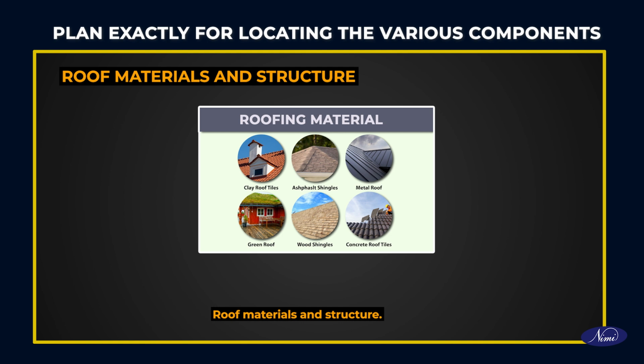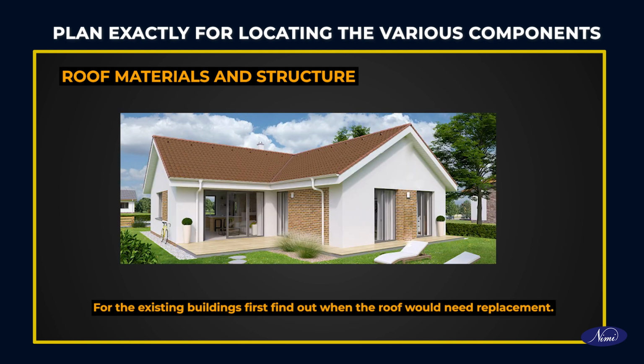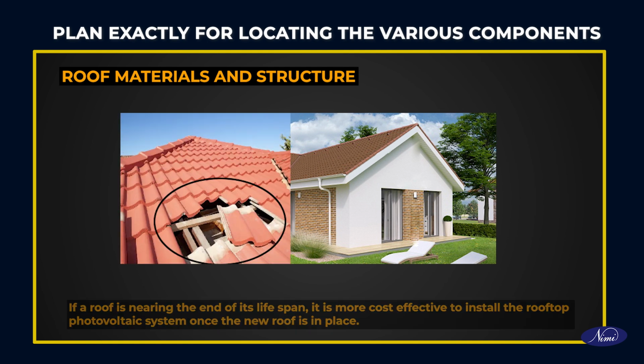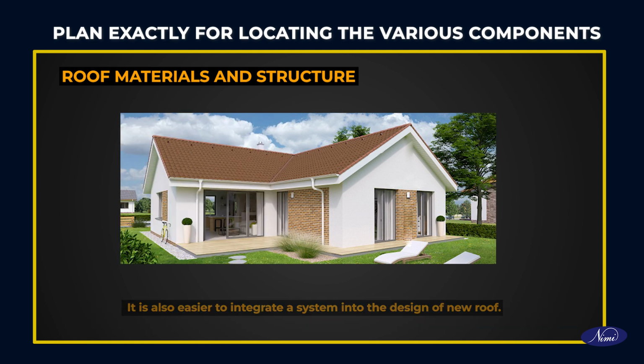Roof materials and structure. For existing buildings, first find out when the roof would need replacement. If a roof is nearing the end of its lifespan, it is more cost effective to install the rooftop photovoltaic system once the new roof is in place. It is also easier to integrate a system into the design of a new roof.